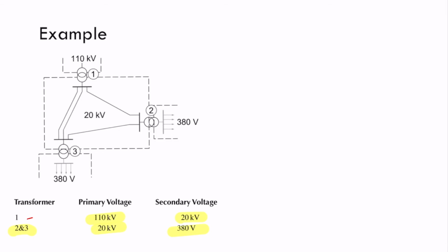So how do we start? Remember, the first thing that we have to do is select the power base. In this case, I don't have a reference of some power consumption. This is a very simplified model. If you have a reference of the power consumption, try to find units very close to these values. I will assume the consumption is around 1 megavolt ampere, and then I choose 1 megavolt ampere.